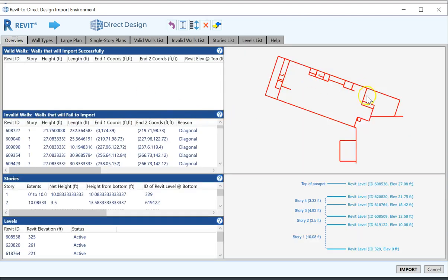Okay, now all of our structural walls are there. There are some other ones that are also there that we're going to have to filter out differently. And so now we will proceed with that. But by doing the exclusion on wall types, we were able to filter out some of the walls that we don't want. Now what's the biggest challenge you can see right up front?